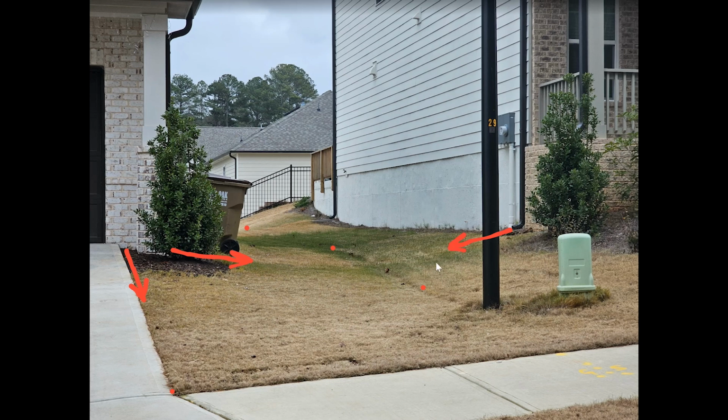These are about 2 to 5% slopes, or 2 to 5% grades coming from the house. And so from that high point, the water's going to tip back into the back there, and then it's going to tip up via the swell again to the driveway sidewalk corner. I think in this subdivision here, the right-of-way was very close to the sidewalk, so that's how it's working there.